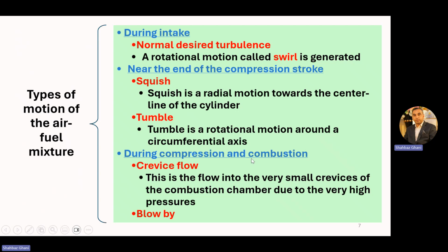Then during compression and combustion, we have crevice flow. This is the flow into the very small crevices of the combustion chamber due to the very high pressure. There are a lot of crevices in your combustion chamber. These crevices may be in the head and the body between the gasket, or where you have placed the spark plug or the fuel injector, or between the piston walls and the cylinder wall.